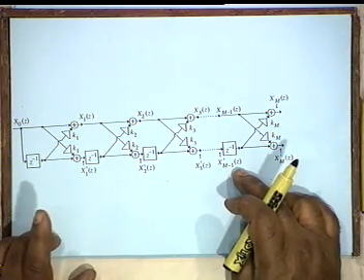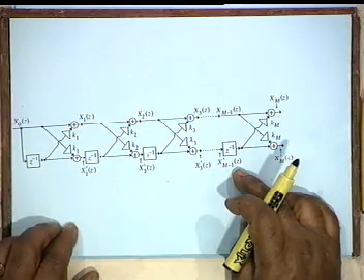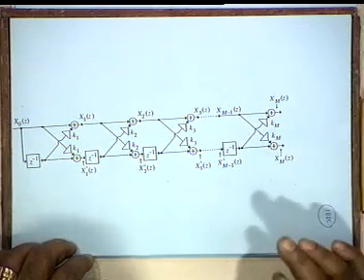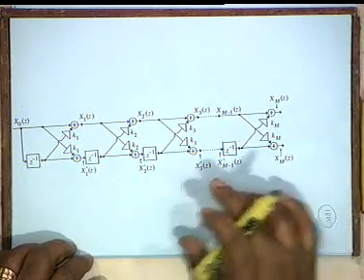So, the highest power in the transfer function, the degree of the transfer function, should be capital M. Number 2, since there is no feedback, it should be an FIR transfer function, it is all feed forward. Number 3, the constant term in the transfer function, that is the term which does not involve any delay, should be equal to 1.